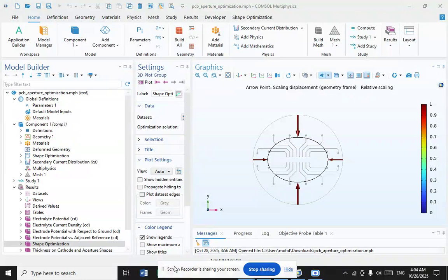The electrolyte is a solution of a salt whose cation is the metal to be coated, and the anode, or the positive electrode, is usually either a block of the metal or of some inert conductive material. The current is provided by an external power supply.